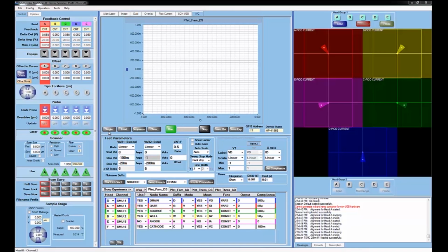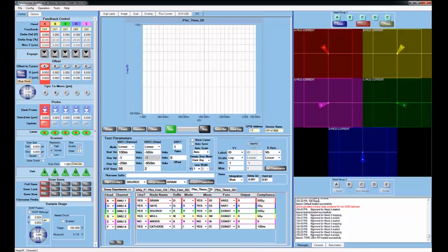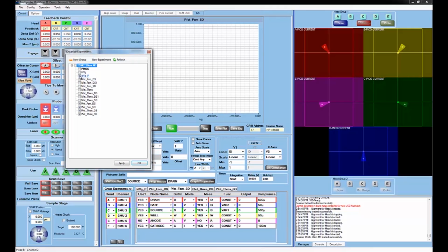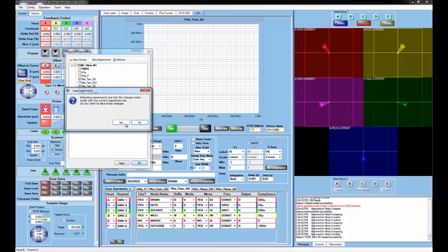When it is time to run measurements, the user has the option of running a single measurement or repeating it, clearing or appending the data on the graph, and running one or a sequence of measurements. When sequence is selected, IVC will run each measurement to the right of the first selected measurement, starting from the selected measurement. You can choose a group of experiments to show in order to select the desired sequence of measurements to run. This is helpful when selecting between N and P type transistors or different kinds of devices.